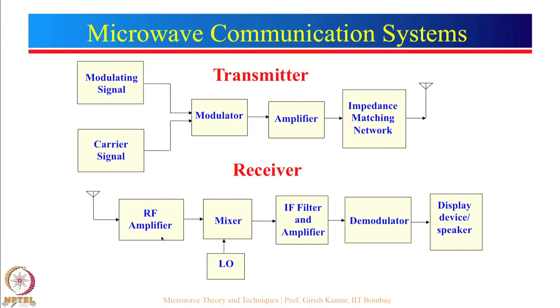So, that is why we need to have an amplifier which may be amplifying the signal by 40 to even 80 dB also, which really comes out to be 10,000 to even million times signal to be amplified. And then this signal goes to a mixer. Now, this is one block diagram of a heterodyne receiver. Not all the receivers use this particular concept, but nevertheless this is one of the most popular concepts. So, this is a heterodyne receiver.